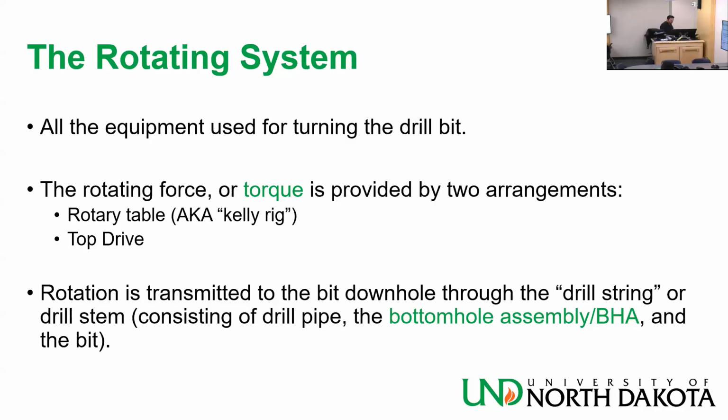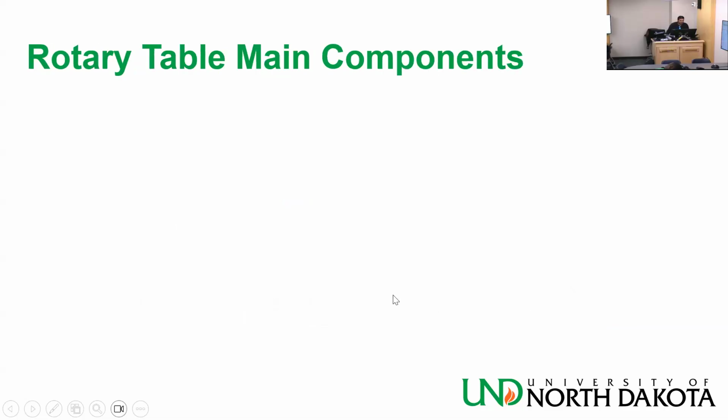It happened in a rig that I was at that they got stuck and then they couldn't get unstuck, and they had to cut the drill string and recover what they could. And obviously they lost the BHA and they had to cement it in place and then go sidetrack around it. And they had to pay something like 900,000 to the LWD company because they basically lost it downhole. And it wasn't even insured. If it was insured, it would have been like 700,000, still a lot of money. But yeah, big part of the drill string.